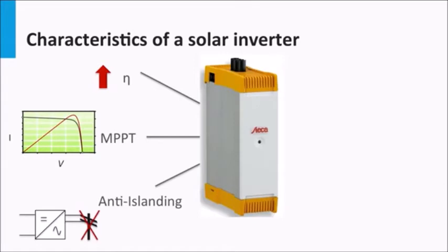Grid-tied inverters are expected to have active islanding detection capabilities. Islanding refers to the situation in which the inverter in a grid-tied setup continues to power the system even though the power from the grid operator has been restricted. Due to safety issues, islanding needs to be prevented. Therefore, inverters are expected to detect and respond by immediately stopping from introducing power into the grid. This is also referred to as anti-islanding.